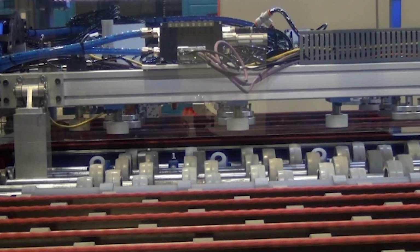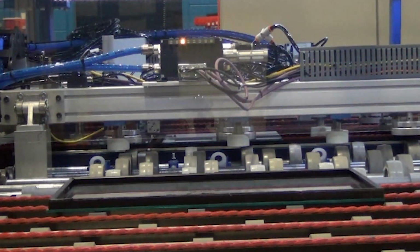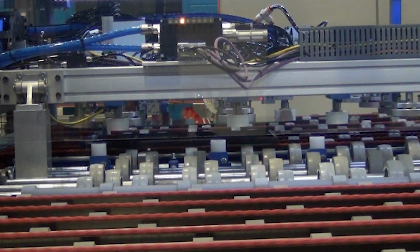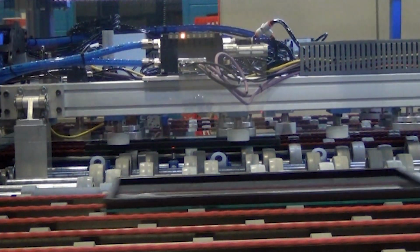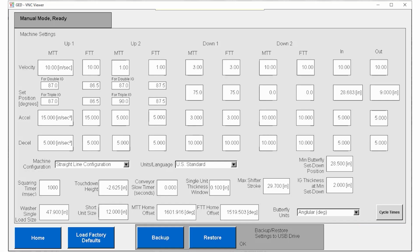The squaring timer keeps conveyor 3A running in reverse for a short time after squaring PE1 is tripped at the end of the squaring process. When making triple pane units, the outer light will transfer into the topping station, and then conveyor 3A will run in reverse to drive the light into the side stops to square the outer light with the center light, which is suspended above. Generally, this is set to 0 milliseconds, but it could be used if necessary to ensure precise squaring.